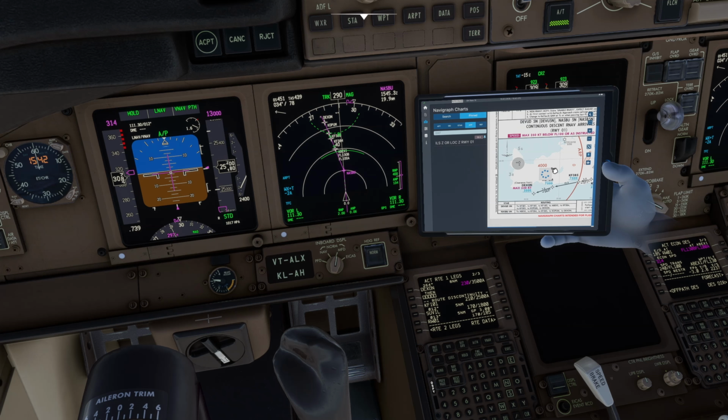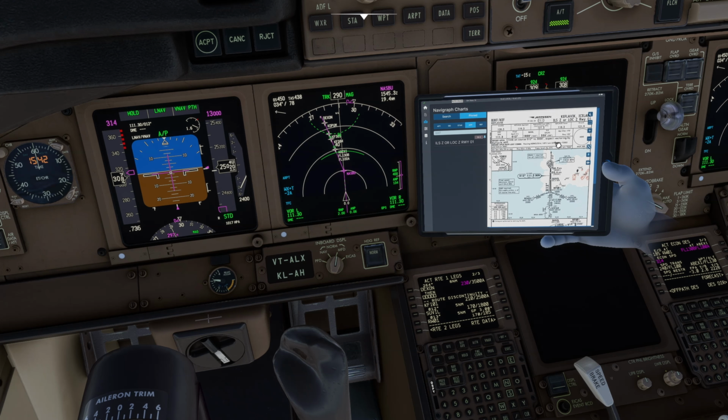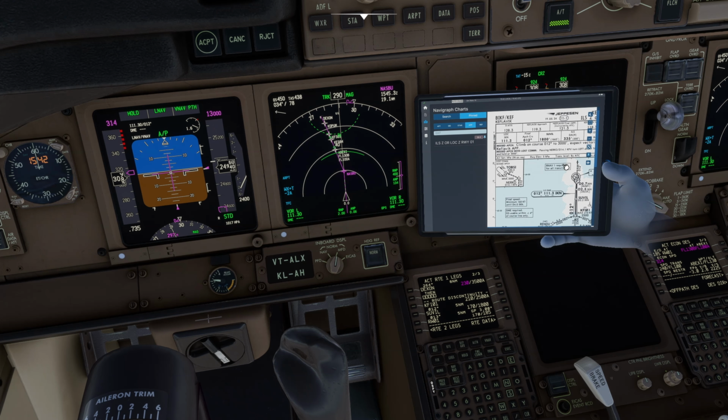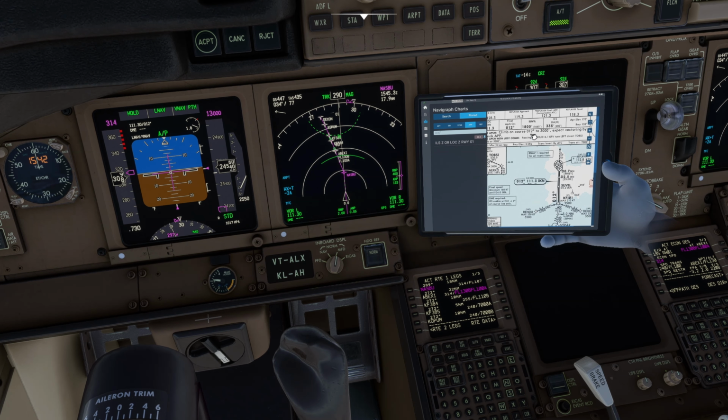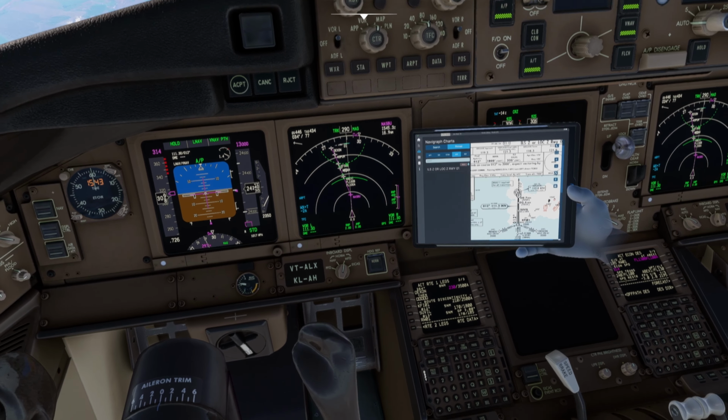And for the approach, ILS approach runway 01, frequency on the nav radio page is 111.3 with course 012, cross checked. Final approach point is at Sewell at 1800, which is cross checked here on the FMC. Minimums is 335, so I need to set that.